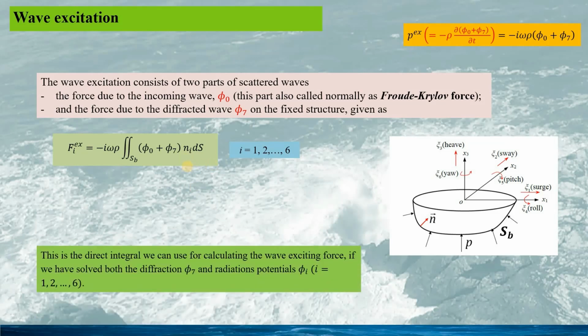The wave excitation is defined as the wave excitation force acting on the supposed stationary structure, while the structure motion has been considered in the radiation problem, thanks to the superposition principle. Thus, this wave excitation would be independent of the structure motion.